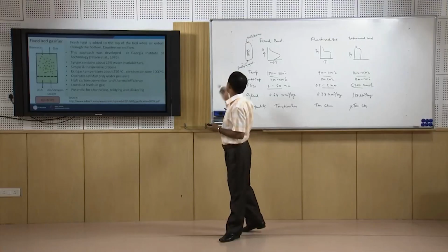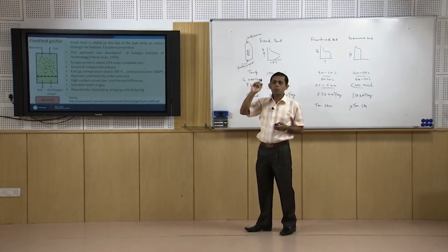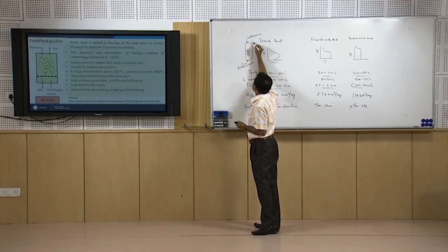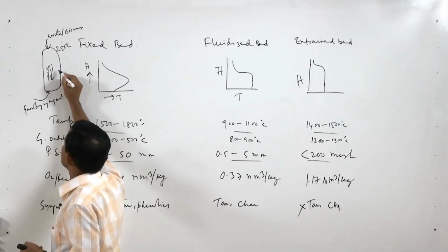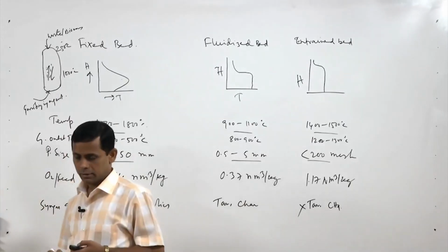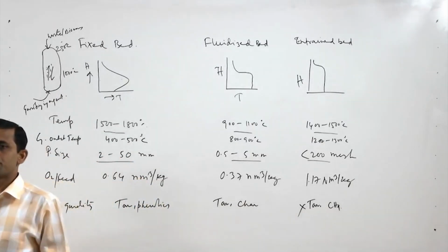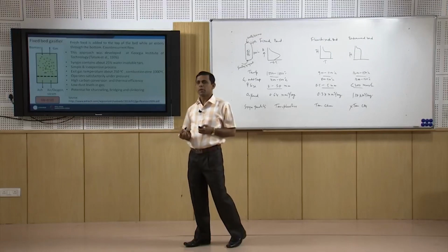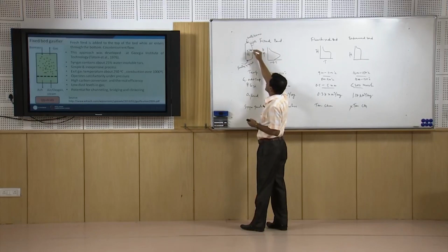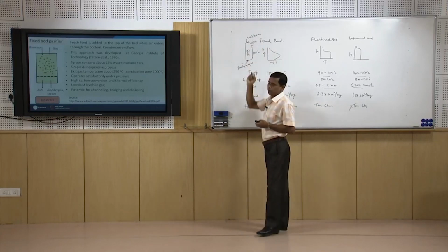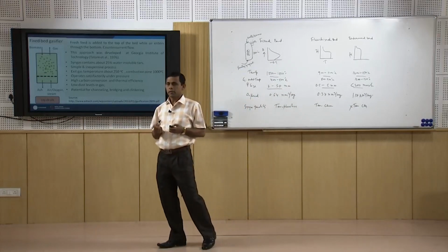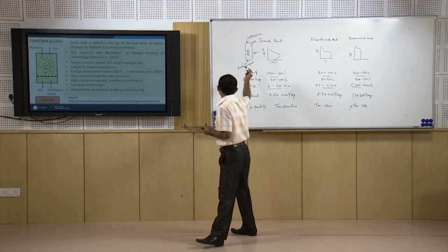So, these are the disadvantages of this process, and another most important disadvantage is that the outlet temperature is 250 degree centigrade, whereas the inlet temperature inside the combustion zone is around 1000 degree centigrade. This is for the updraft fixed bed gasifier for biomass and waste. So, due to this low temperature and less contact time, the syngas will contain a high amount of tar, around 25% tar in the case of updraft biomass gasifiers.